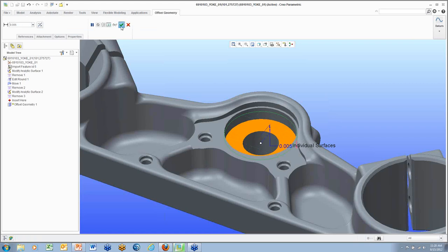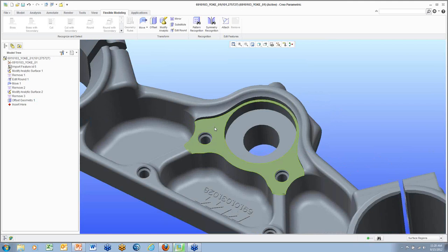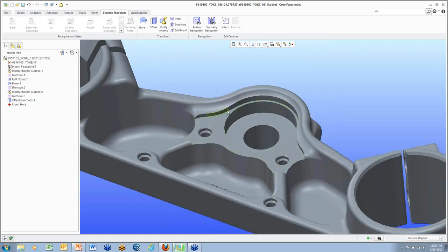And there we go. Even in parametrics, you'd simply select that surface that you want to create a plane on or extrude on, create a circle, and extrude cut. Not a big deal. What might be a little bit tougher to work with is this particular surface here, okay? We do have some interesting rounds over here that the sketch may have created. And in order to recreate that, it might be a little time consuming.